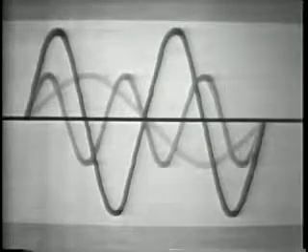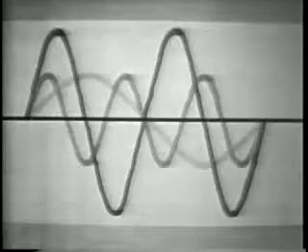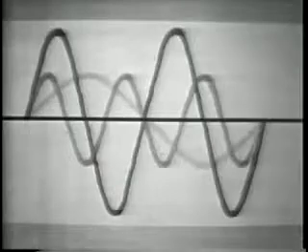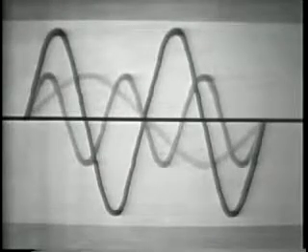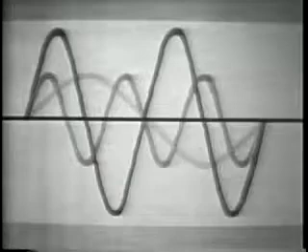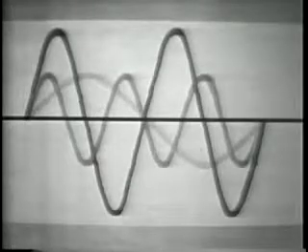Because what you see on a scope is not just the carrier, the sidebands are also present. To show the carrier by itself while the sidebands were present, the display would have to look like this, showing all three frequencies in their individual forms and relationships simultaneously. But as you know, a scope cannot show three different voltage values simultaneously. It shows the instantaneous summation of these voltages.